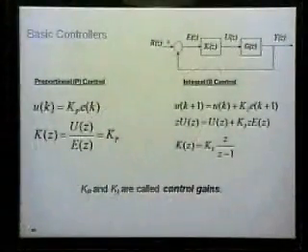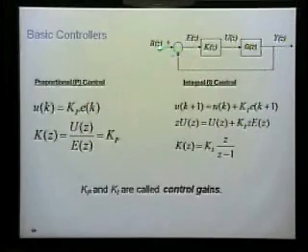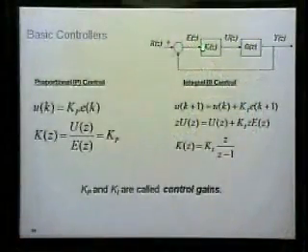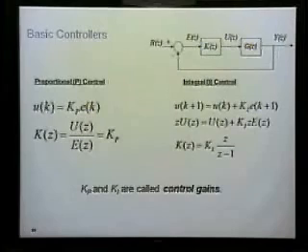Oh, because in this system right here, we get the output at time k plus 1. That's immediately subtracted from the input, the reference value, which is mostly constant for our purposes. So we subtract it from there, and we're still at time k plus 1. Then that gets fed into the controller. Now, does being fed in make it k plus 2? No, we haven't changed any time yet. We only get delays from the systems. This system here has some delay, it's a first-order system. This system over here has no delay.